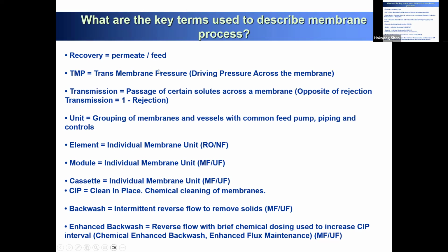Recovery is very important because when you have a higher recovery, your final brine concentration of salt is very high. So you create calcium carbonate, calcium sulfate, a lot of inorganic scaling crystallized, so that the membrane is damaged.